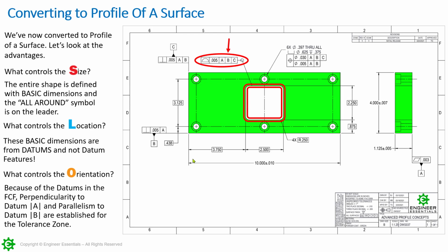That way we know that the first requirement is that A is locked down. Remember, 6 degrees of freedom. So it would go up against the 90-degree plate. That is also a datum simulator, just like the granite table. We would secure it up against there and then slide down to the granite table for B, because it's a secondary. And then if we needed to, slide it over to something to stop C. But this is going to lock the part down. Now we can take a height gauge and come in and just simply see, when we touch off on the surface, is it where it's supposed to be?